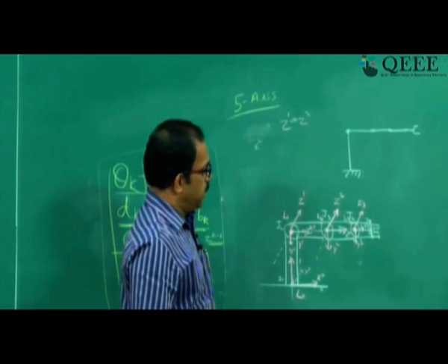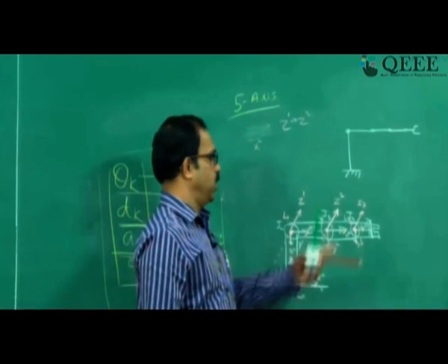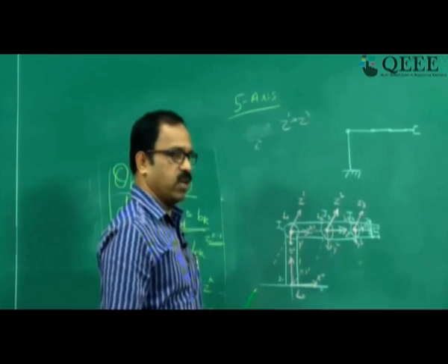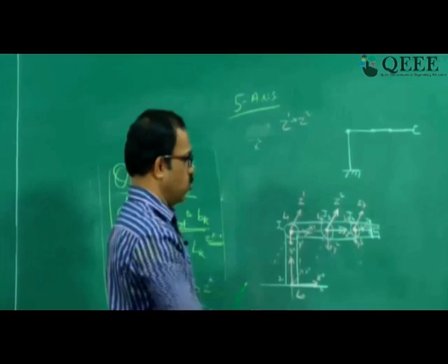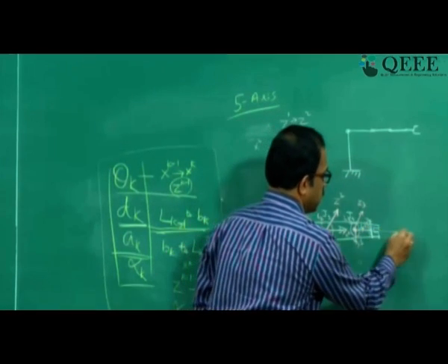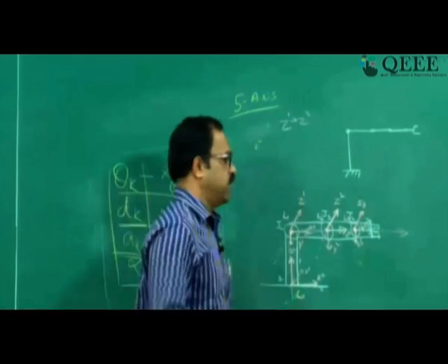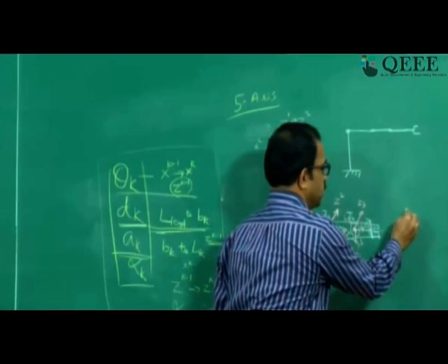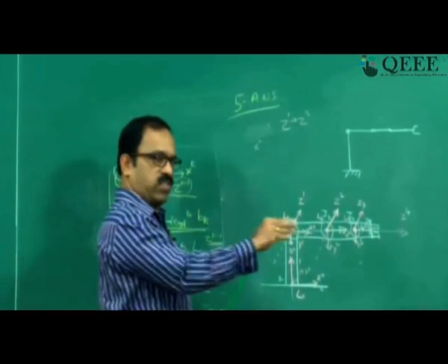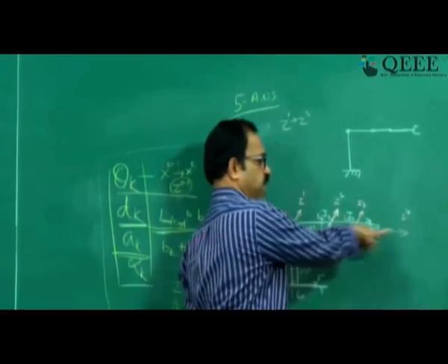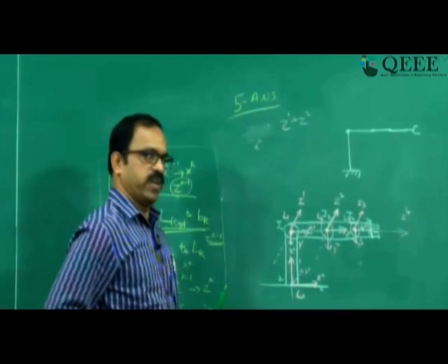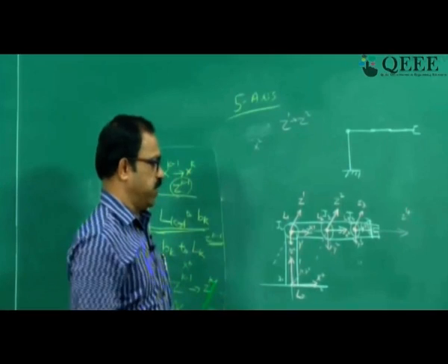Now a slightly interesting problem is coming up. Look at the next joint. The next joint is a roll joint. This roll joint has an axis like this. This is the Z axis. So Z4 is like this because it's a roll axis. We need to find the origin of this coordinate frame. So where is the origin of this coordinate frame?